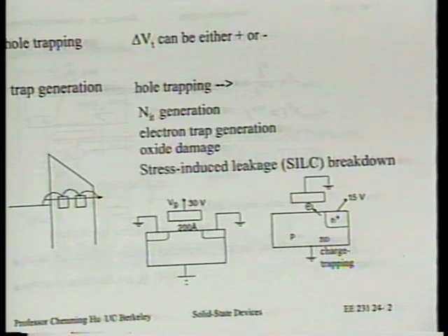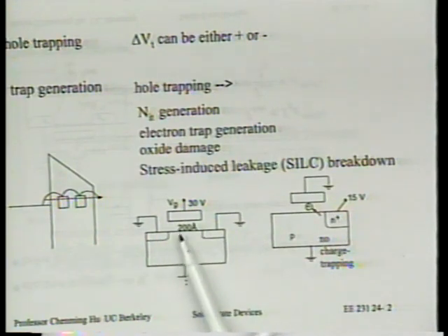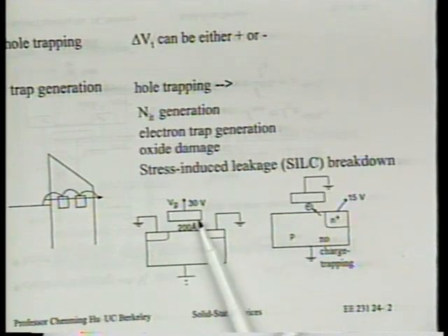But it's particularly measured in this simple case. Source, drain, and body are grounded. And when you apply positive voltage to VG, of course, the surface is inverted. You essentially just have a ground plane all over the surface of the substrate. So if you keep raising the gate voltage, at some point the oxide will rupture. And let me tell you, this will happen at about 30 volts. In other words, 15 volts for 100 angstrom thickness. That's actually a very important number to remember, a useful number to remember. 100 angstrom can tolerate 15 volts if you're just looking at 1 second or a very short amount of stress.